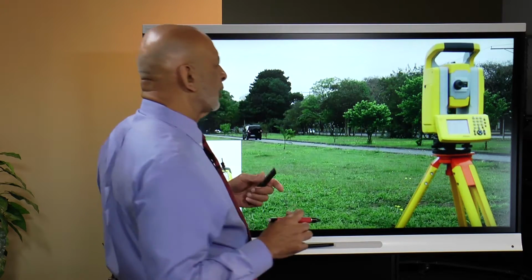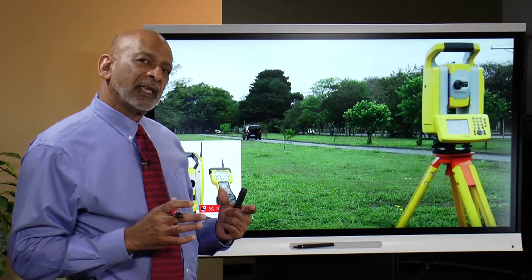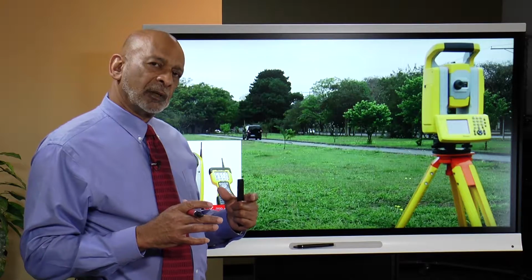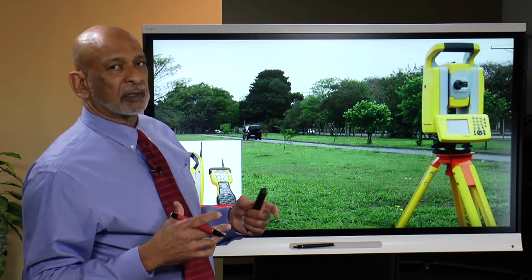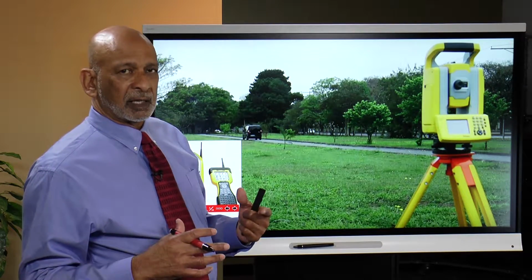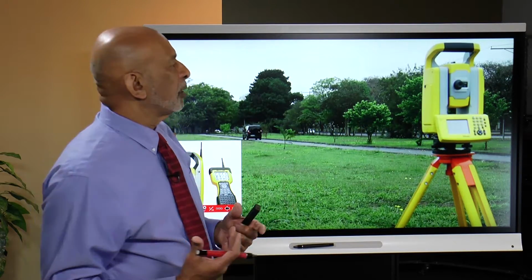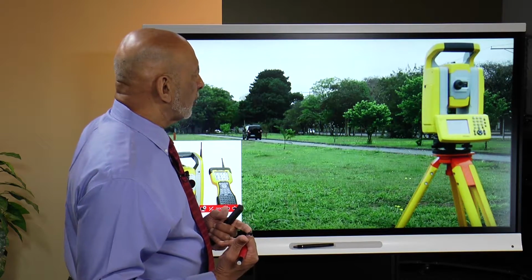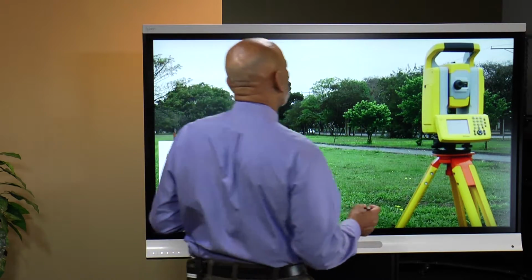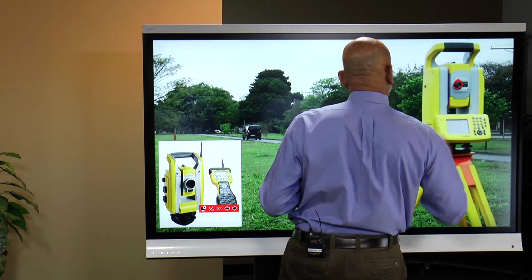So these instruments also have circles of glass, but now they have electronic coding of different types. Sometimes there's an optical reading system, sometimes there's a magnetic reading system, and the kind of graduations placed on the circles vary depending on the technology used by the manufacturer. But here's the eyepiece of the telescope.